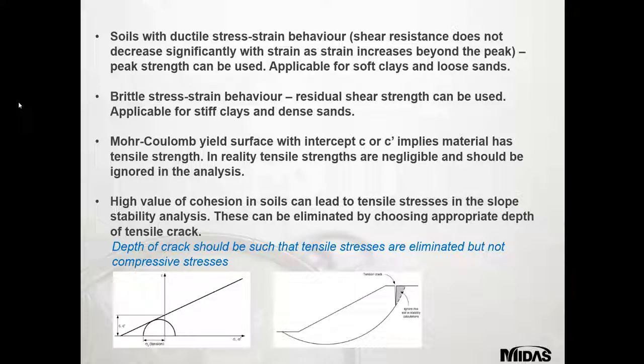So in soft clays and loose sands, which have ductile stress strain behaviour, peak strength can be used to represent the shear strength in the analysis, whereas the stiff clays and dense sands have brittle stress strain behaviour, and in this case residual shear strength should be used.